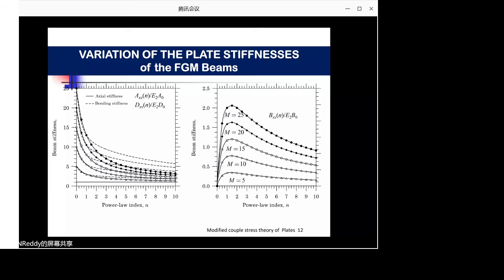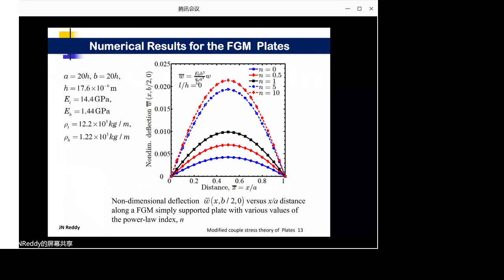So that way you really get rid of any kind of stress concentrations. That is the main idea of these FGMs. Doesn't mean we always use FGMs. We still use layered composites in many structures, but this is another area that has come up in the last 2 decades. And I'm just showing you the results for that functionally graded material.